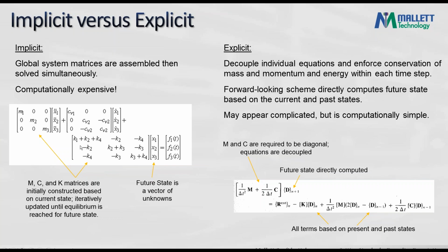An implicit solver requires us to assemble that entire matrix, ideally hold it in memory, invert it, and proceed with solution. Once we have our solution of unknowns here, assuming it's a nonlinear problem, we have to plug them back in, reassemble this full global matrix and solve it again. And keep doing that until equilibrium, until we get the right forces out the other side.